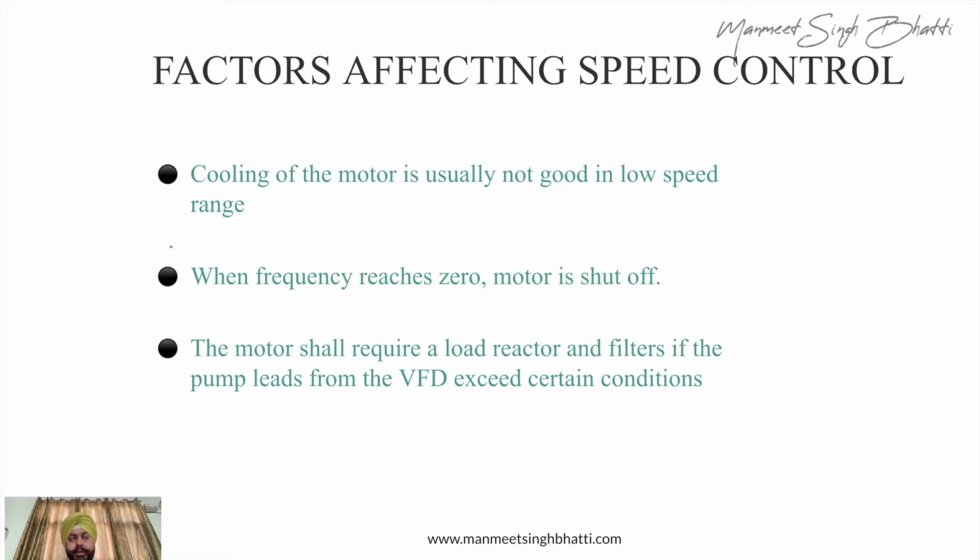So it's always recommended, whenever you are putting VFDs in an application where safety is very important for the machinery, that you lock the VFD for a minimum RPM. The RPM should not drop below that irrespective of any conditions. Otherwise, if the RPM goes below that, the motor will switch off, your load will be off, and there could be some kind of problem in the system.